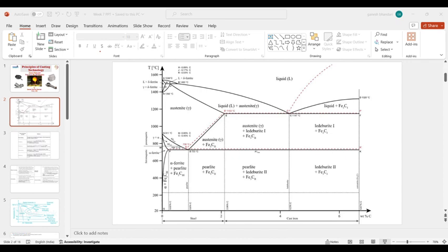That can depend on the properties you desire. You can control your carbon percentage on the surface according to that. Those types of processes are known as surface heat treatment processes. Although we are giving temperature to the whole sample, the reaction is happening only at the surface of the sample. After that, we generally go with normalizing or quenching process after surface heat treatment processes.